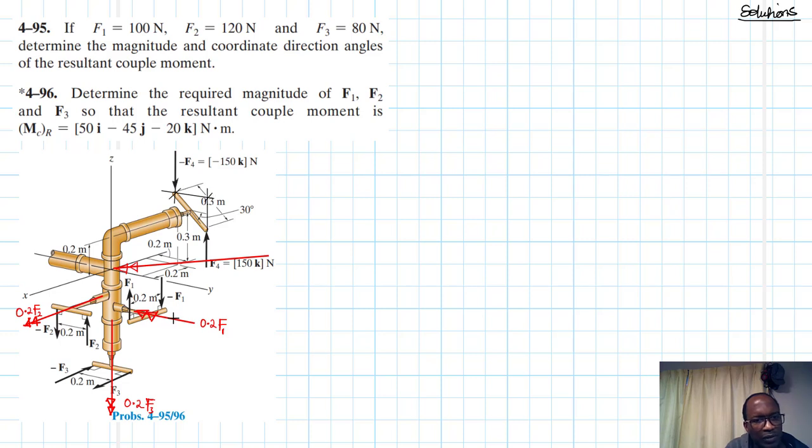So now we have this particular perpendicular distance. This is the distance that we want. Alright. So what is this distance? The angle is 30 degrees with the y-axis. You've seen this angle here. So this is going to be equal to the length, over this particular distance there is our arm where the forces are connected, which is 0.3. So it is 0.3 cos 30. Great.